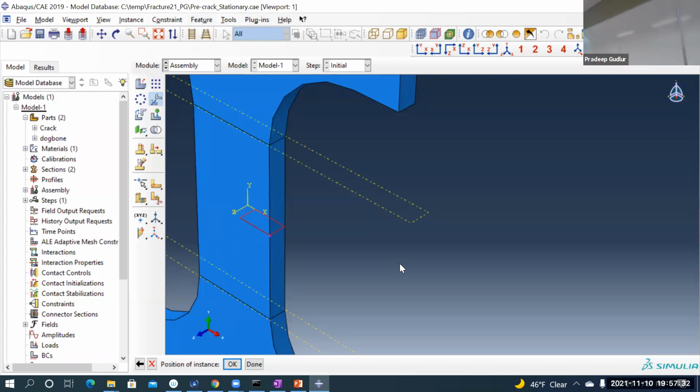So that's the external crack. The surface is exposed there. The crack is on the surface. Say done. And if you go to the wireframe mode or the translucent mode, look for a cube with global transparency. For me, it's at this end, just beside the colors, the assembly defaults. If you click that, you would see the crack appearing transparent on that part.